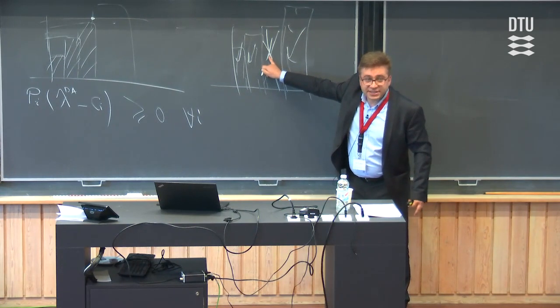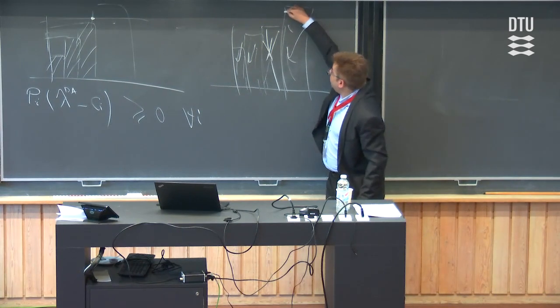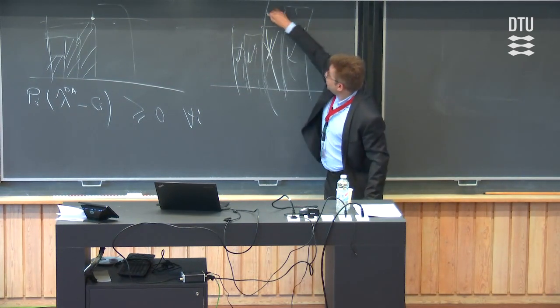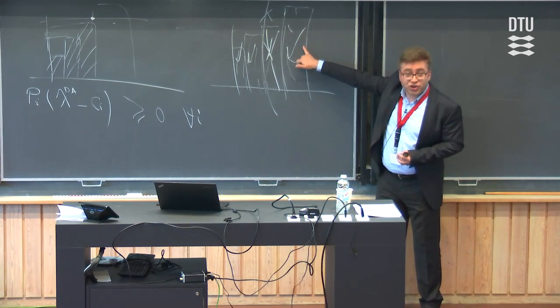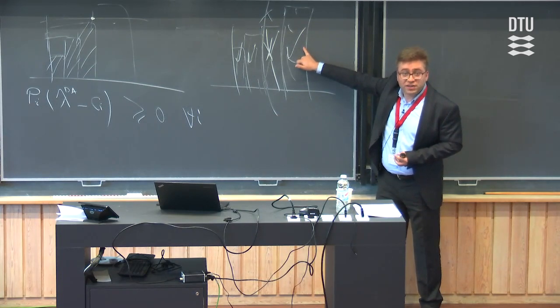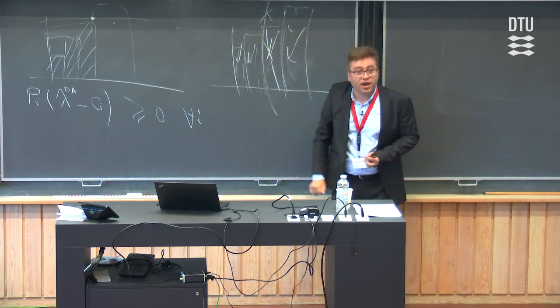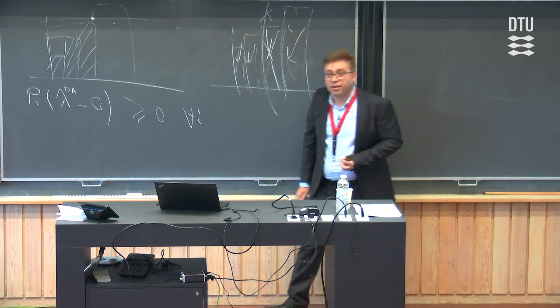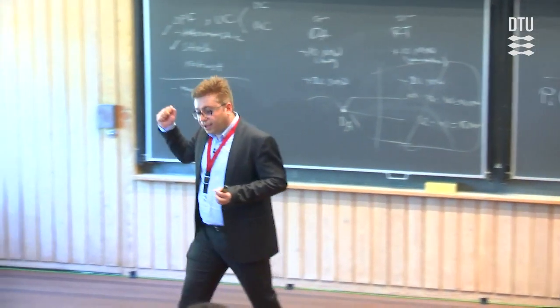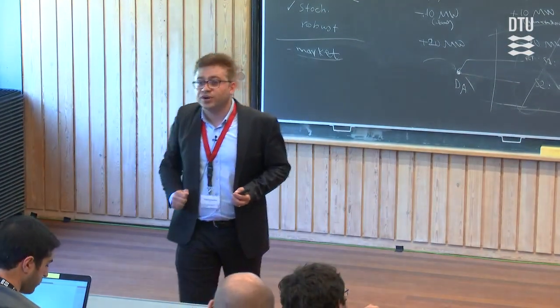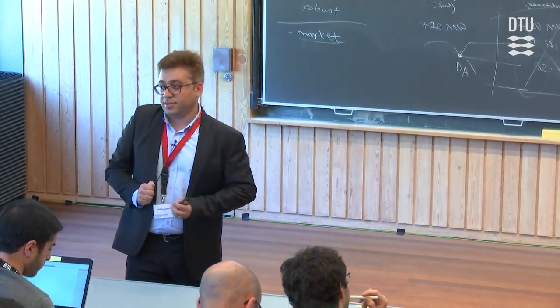But the bad thing is that the market price in day ahead will not be here. It will be somewhere here. It means that we dispatch an expensive generator in day ahead while we will pay that generator at a lower price in day ahead. So stochastic market clearing violates the cost recovery in day ahead.